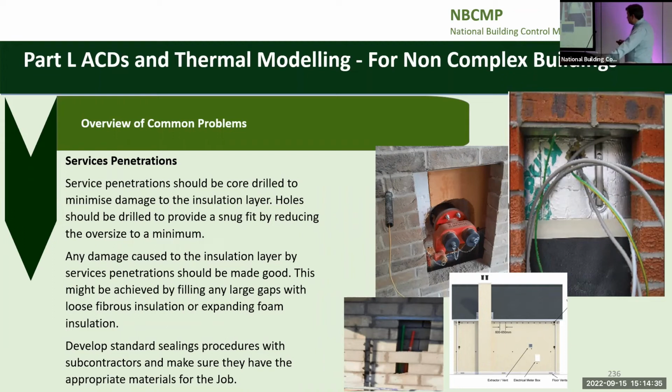And you can model those junctions as well. And you're looking for the assessment on that report as well for that area. And there is a requirement in there that you cannot have more than 2 service areas on these aggregate sites, as they may create a fire hazard. And the other thing too is you're going to have a cold bridge in here unless you provide rigid insulation behind the back of your box.